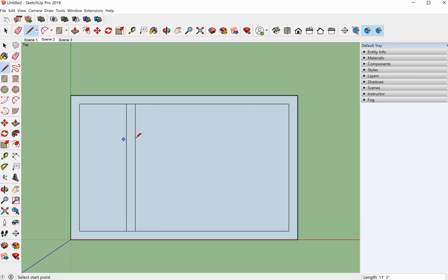So now you'll want to make the 2 actual interior walls. And the first wall is going to be 4 feet 8 inches. So that wall will be at this bottom edge. So start from one side of the 2 lines we just drew. So the wall, start out one side at the bottom here. Click once, hover your mouse and type in 4 foot 8 inches. Go to that point and draw a horizontal line to the other side of the wall.